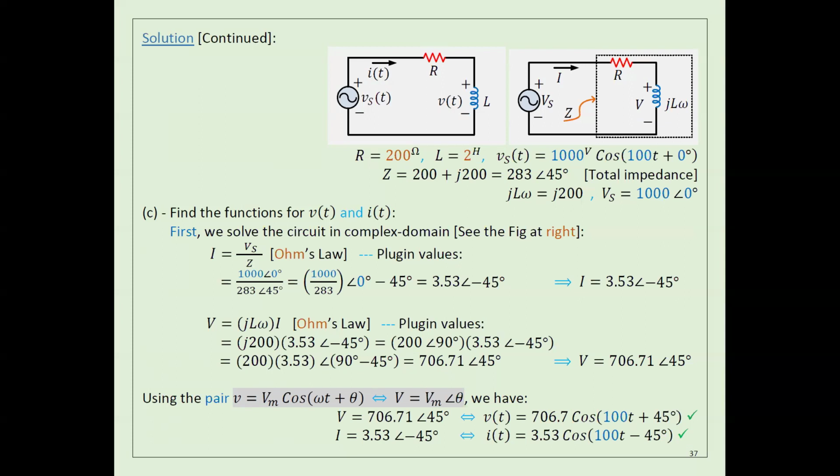Yeah. Once you know the current, can you calculate the voltage across this resistance? Again, it's not resistance. Across this impedance, if I know the current, can I calculate the voltage across this impedance, which you can see like a resistance as we did before? Okay, how can you do it? You know the current, you know the impedance or the resistance. Can you calculate the voltage across it? Ohm's law. So all you have to do here is, as you see, the voltage is equal to I times the impedance. That's it.